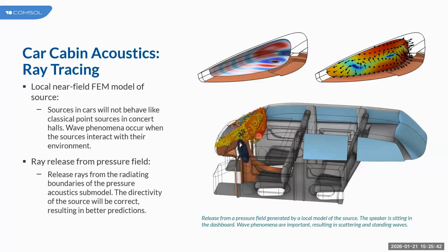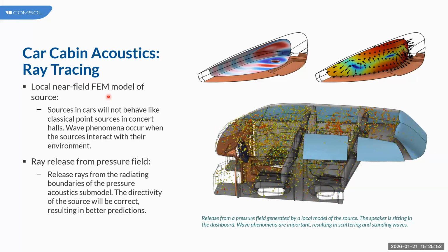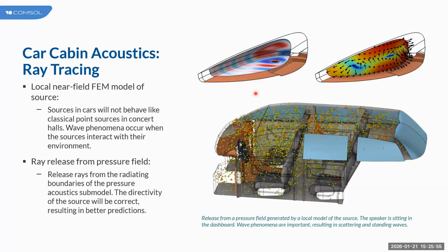So this model shows how to model the car cabin acoustics using a hybrid FEM ray approach. In this example, a high fidelity model of the loudspeaker driver is modeled, and the near field solutions are computed in the frequency domain using the finite element method. This is further coupled to a large scale simulation where we use the ray tracing approach. The coupling between the finite element model and the ray tracing is done on a surface.